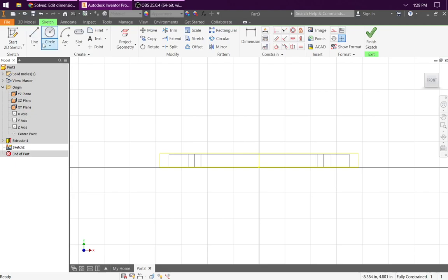So we'll go back to Sketch, and I'm going to do an arc, and I will use the center point arc. And we're going to start on the bottom face right at the origin here. So don't start on the top. You do want to start this on the bottom. Click first your center point, then arbitrarily we're going to keep it on the bottom face. It should snap to it. Any distance, doesn't matter too much, and then we'll click again when we get to the other side.